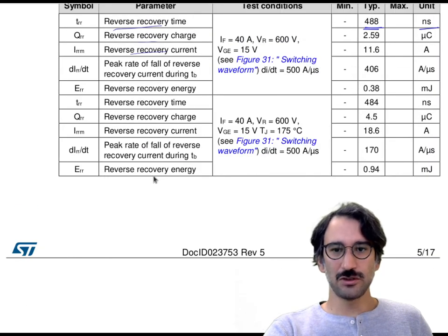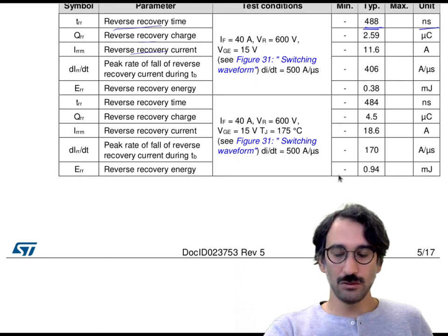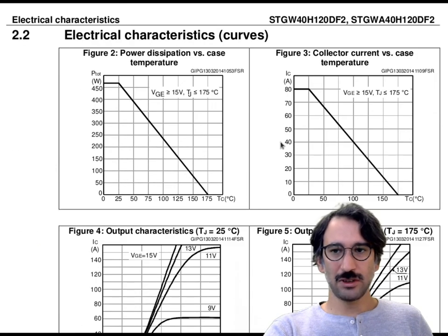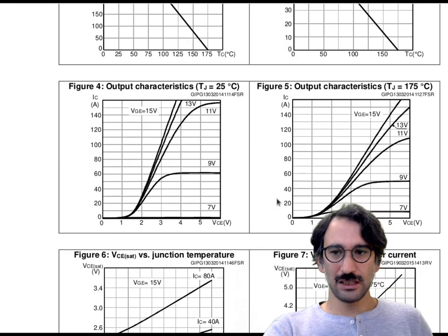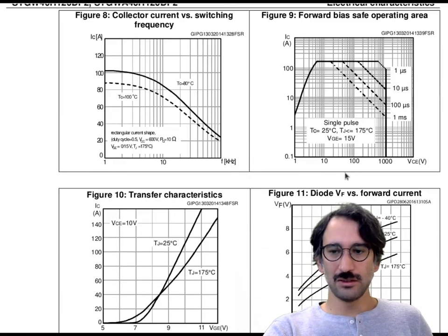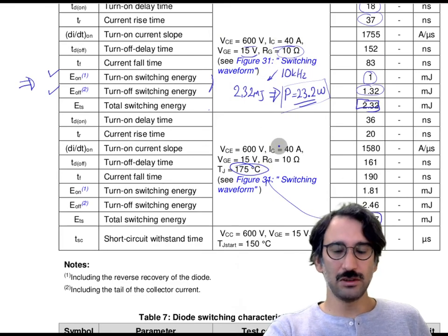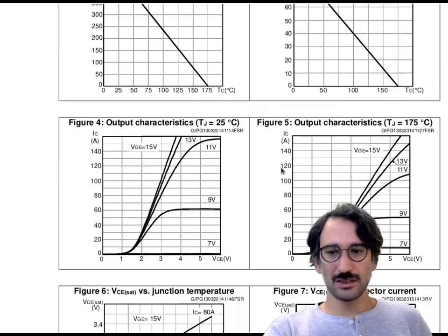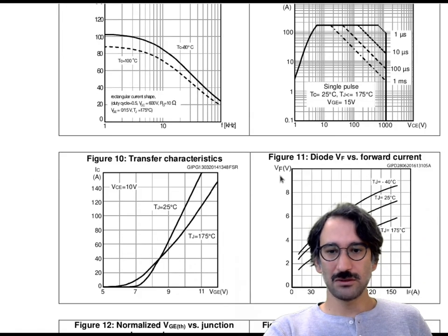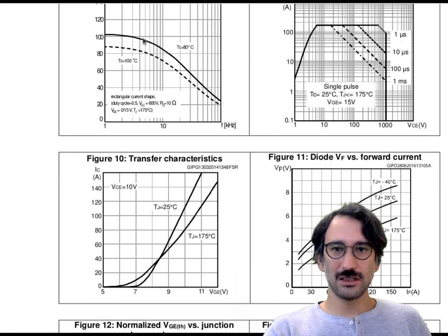And again, reverse recovery energy is how much energy you are losing in the diode switching. And if you look at the next characteristics, they all show how the voltages change with temperature and with currents. Those figures are just given for specific operating conditions, and you can start with those numbers, but once you have a detailed understanding of device operating points, it will be helpful if you can find your operating points through those graphs and check if they are within your limits.